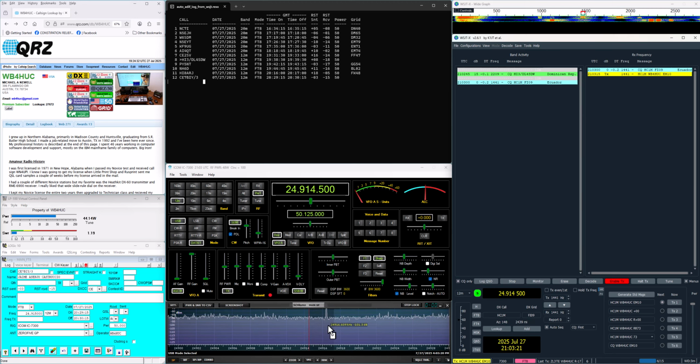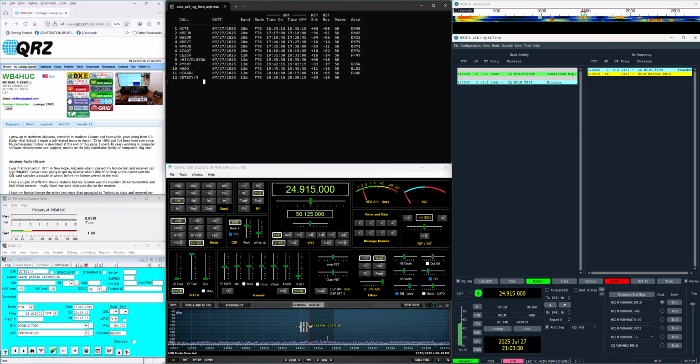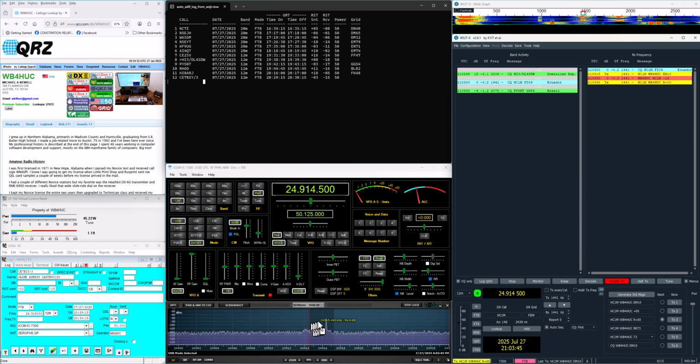You can see that when I'm transmitting, again 44 watts, I'm going to boost that up to about 50, but you can see that the software-defined receiver does hear the 7300 transmitter, but it's at a low enough level that it's not hurting the SDR because of the way this thing is connected up internally. It's the receive signal really that's brought out to the software-defined receiver, but there is some signal leakage, but not much. So let's just see if we can.